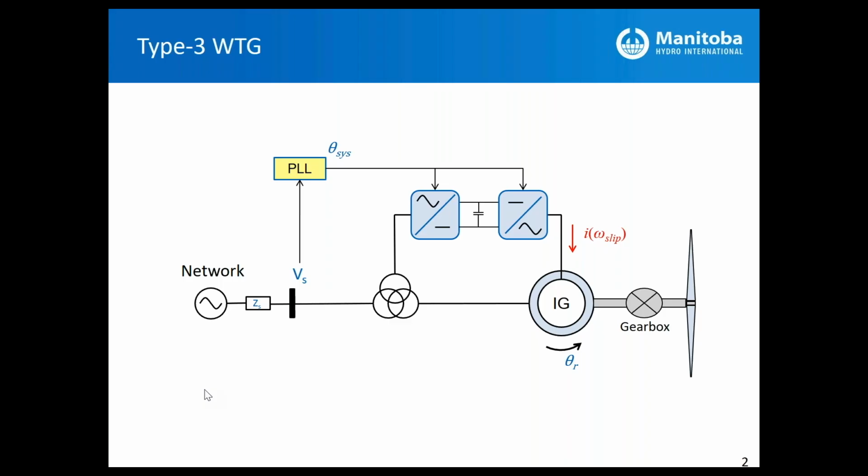The common thing in these types of turbines is that most of them right now are working based on grid following requirements, meaning that even though the controls are trying to regulate active and reactive power levels at the point of interconnection to the AC source, they all use a synchronizing mechanism called the phase lock loop.